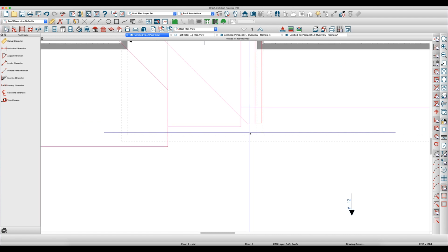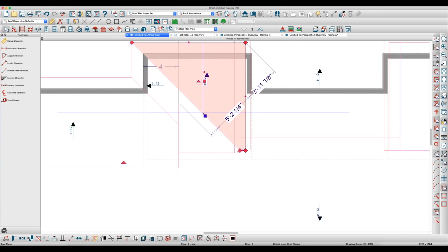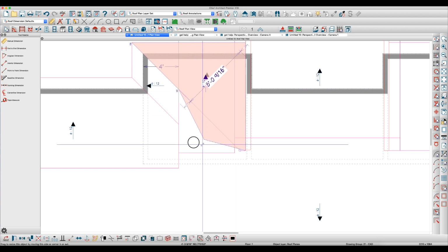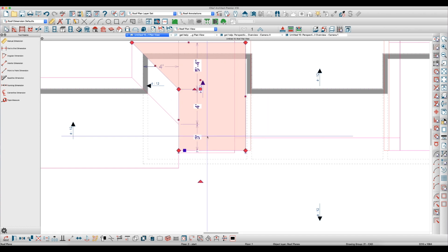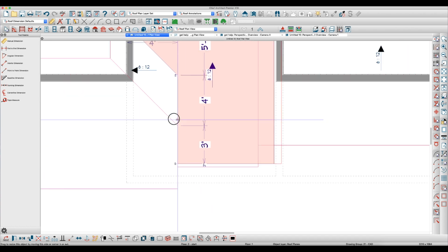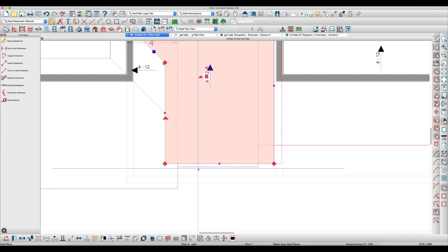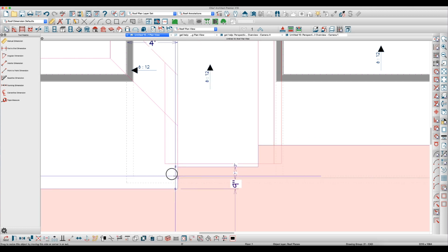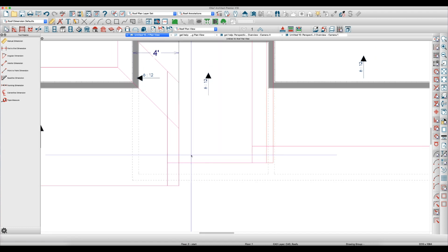And then we have this roof, which we want to break right here on the 4-foot line we have and pull this over till it's square. Just hit cancel for there. Then click here and pull it and hit -12 and 0. Then pull this over until it lines up here. Click here on this ridge, hit 2, click here and let them join.